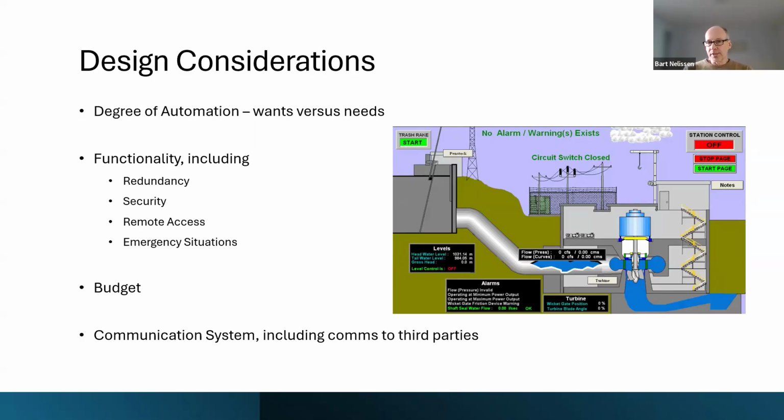Maybe your backup SCADA server should physically not be sitting right beside your primary SCADA server. Because if your primary SCADA server becomes unavailable for one reason or another, your backup SCADA server, which might be sitting across the city, will still be up and running. So that plan and that design is of utmost importance and certainly should be considered in the design considerations early on when you start thinking about rolling out a SCADA system.